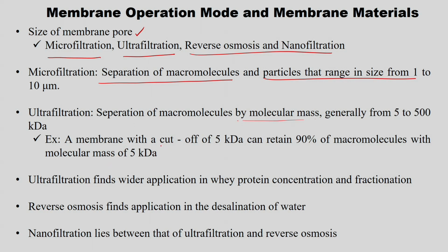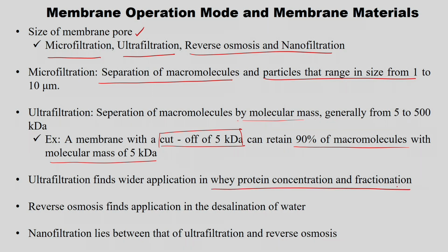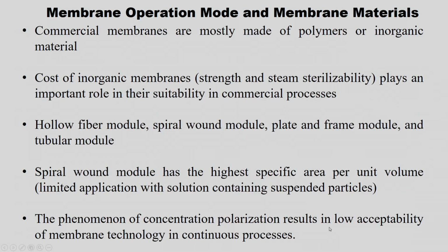So, a membrane with the cut of 5 kDa retains 90% of macromolecules with the molecular mass of 5 kDa. Ultrafiltration finds wider application in whey protein concentration and fractionation, and reverse osmosis finds applications in the desalination of water, and nanofiltration lies between ultra and reverse osmosis. So, based on the application.